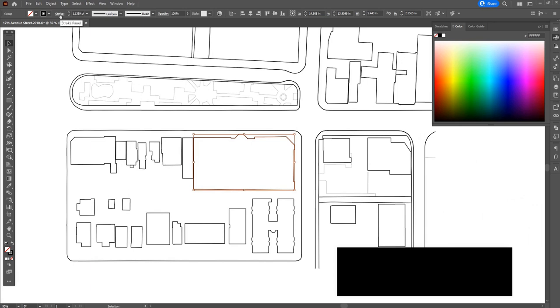From here we can move over to this drop down menu, left click, and as you can see there will be a series of different options in terms of what we can pick for our stroke. We can specify our own number if we wish, but for now let's just try seeing what happens if we pick a 3-point stroke weight. Left click, and just like that, we've now changed the weight of that stroke. We can adjust all of these as we wish.